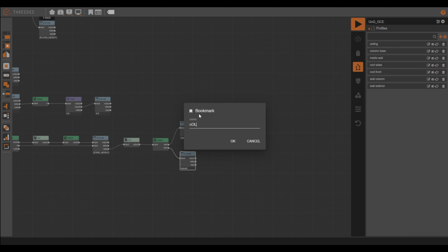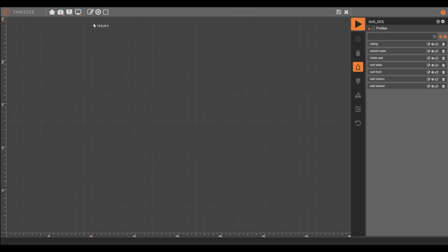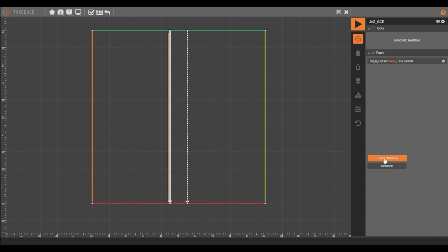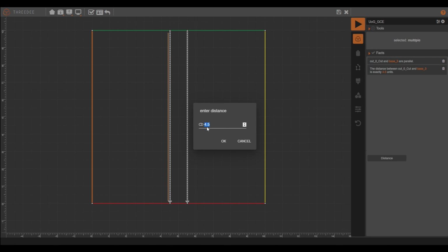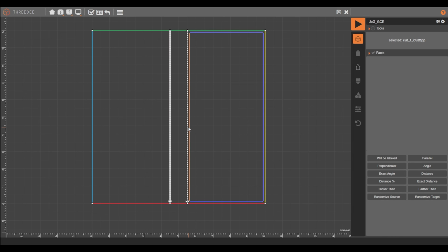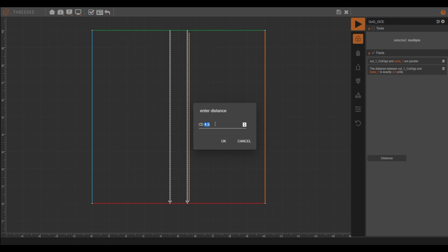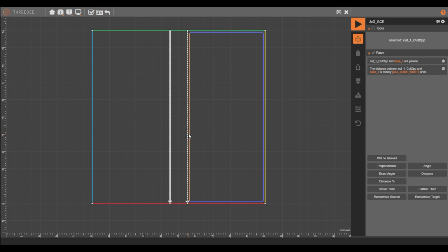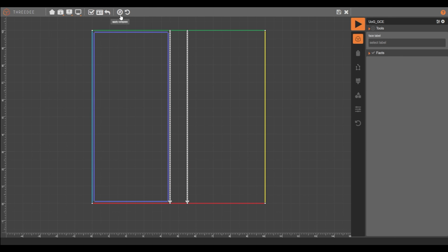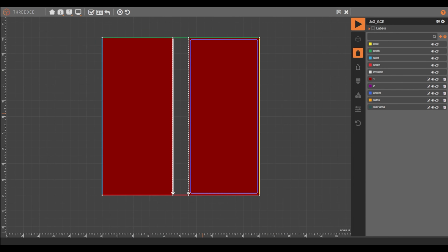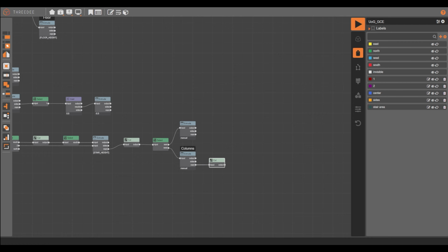We will create a repeat cut and another select node with the labels east and west. From the east, we will create another extrude node where labels north and south will use the profile inside wall. From the west, we will create another extrude that will allow us to start creating the columns. This node will have labels south and north using the profile column base.